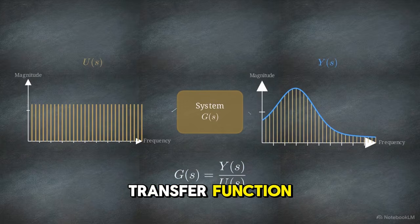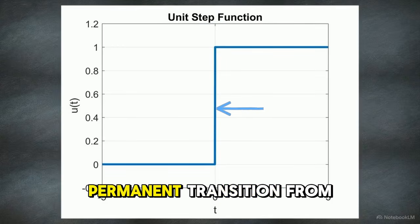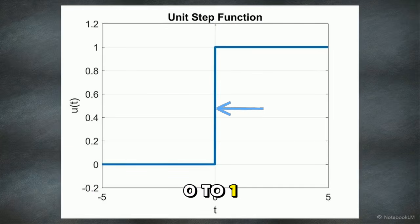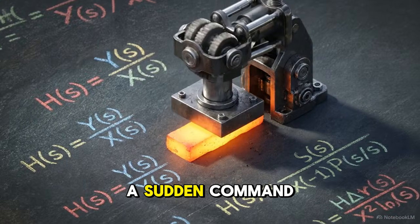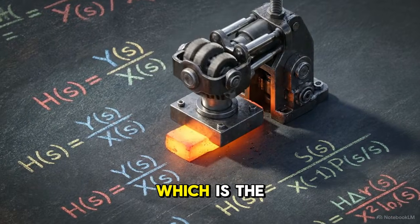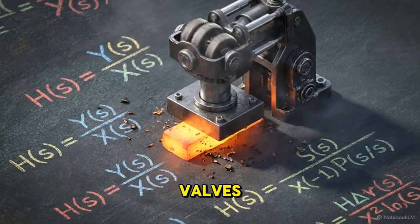unique transfer function. This next chart shows the unit step function, u of t, characterized by a sudden, permanent transition from 0 to 1. The step input models a hard switch-on event. It tests how a system handles a sudden command to change states, which is the most common operating condition for power electronics and hydraulic valves.